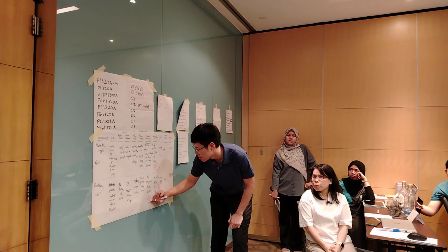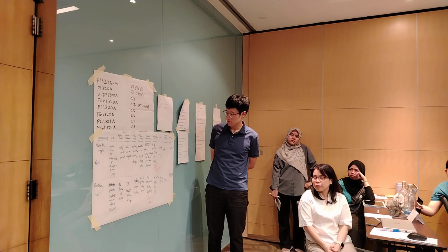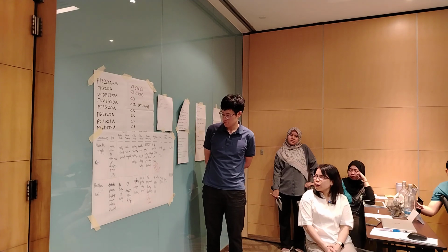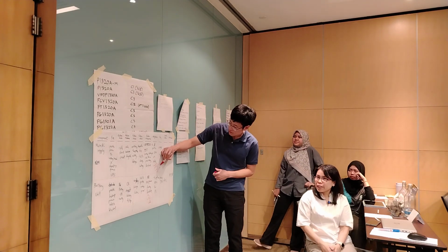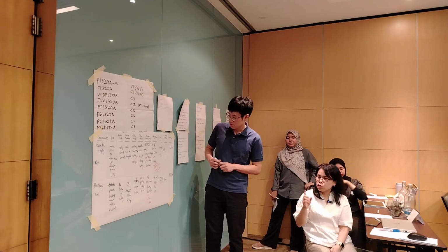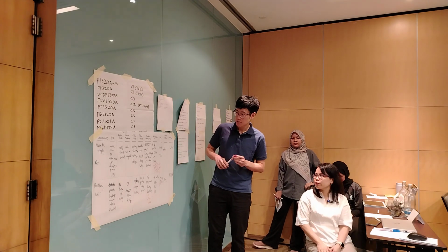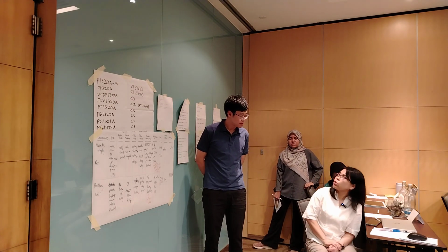So how do the failure consequences play a role in that? Because the more catastrophic, the same, correct, mitigation and frequency. Yes, you are right. Because this one is an SCE, there is an SCE task. Even though it is an SCE task, as I mentioned, you still need to do the charging discharging test, which I didn't see here. That is to ensure that your UPS, your battery is still in healthy mode.